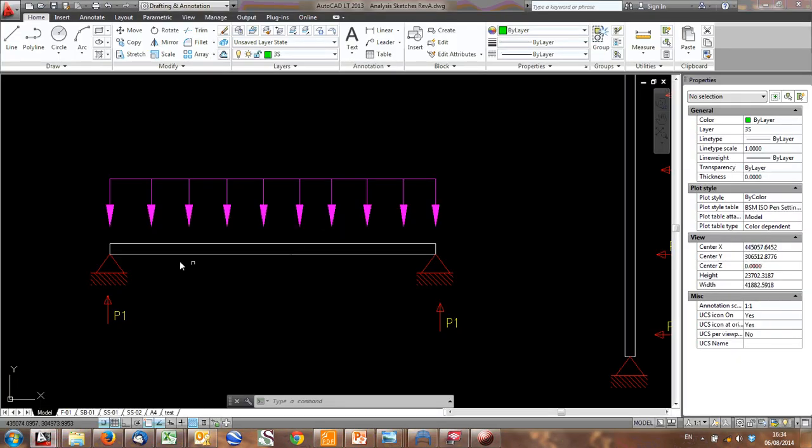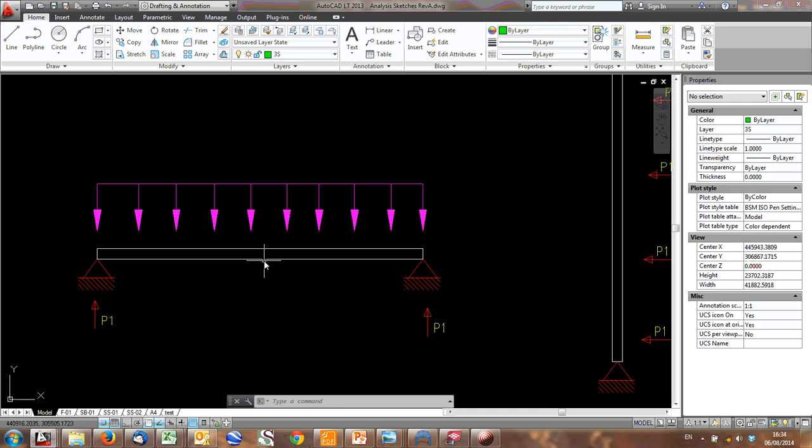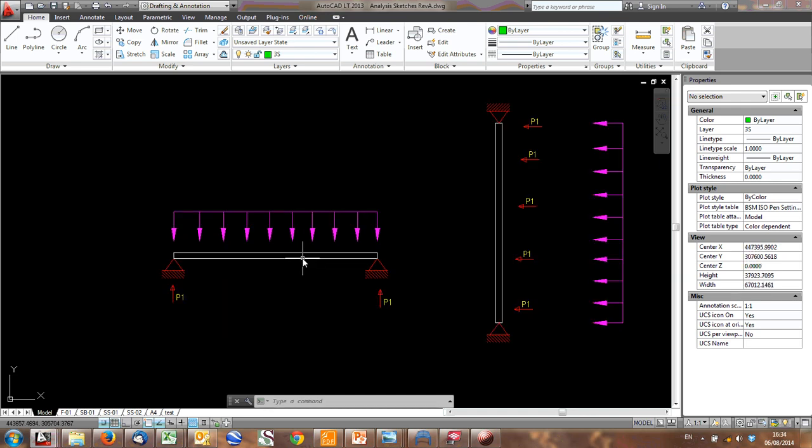You can size it for deflection. You can very quickly get the I required, the second moment of area required to give you a specific deflection limit, whether it's length over 180 or 250 or whatever deflection requirement you require in your code. You can size it and then check for strength. In steel, it's often deflection governed, and then you check for strength.